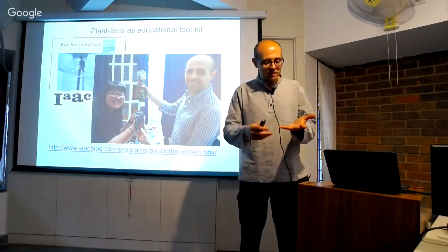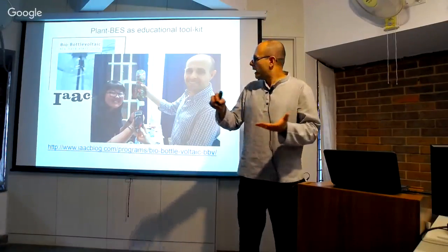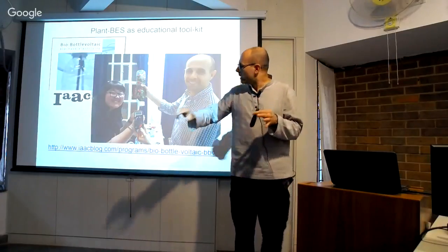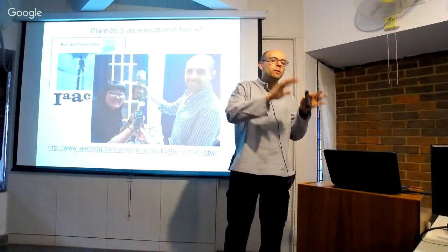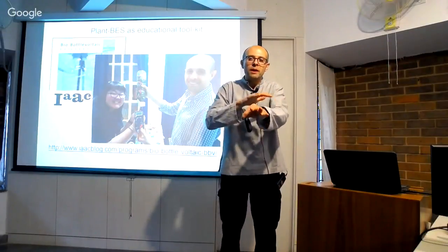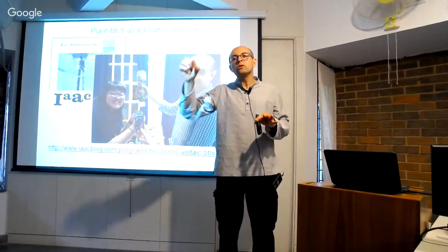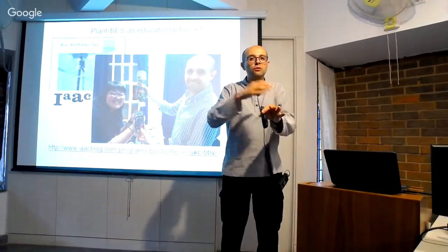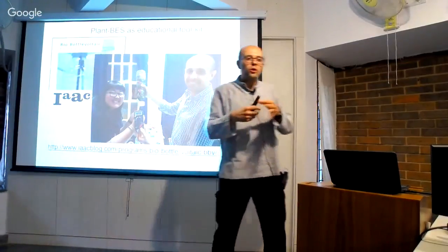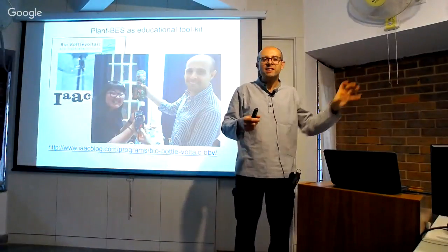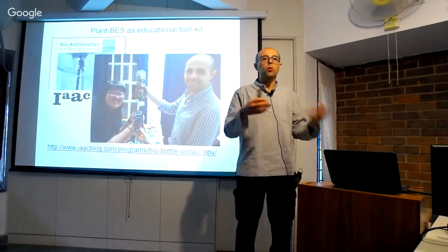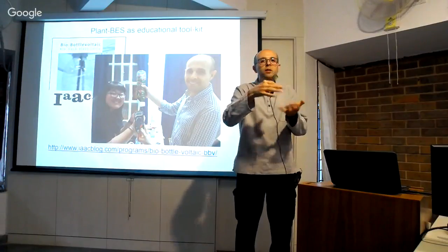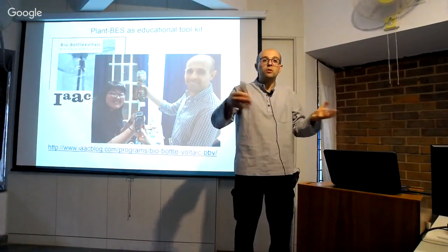They grow very nicely. But more importantly, after a little while, the water forms a layer of aluminum oxide on the surface of the anode. And this compromises a bit the conductivity of the anode. It is not great, but it protects the anode from further oxidation. So we compromise a bit the conductivity, but it still works, and the layer of aluminum oxide prevents the anode from disappearing over time.